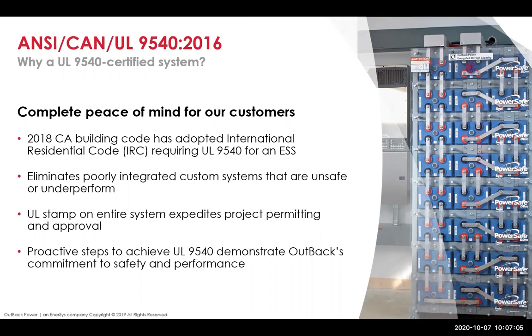So one of the things, even if you're not in California, and if you are in California, let me cover that case first. The 2018 California Building Code has adopted the IRC, the International Residential Code, that requires UL 9540 for energy storage systems. But again, that only applies to lithium-ion based batteries.